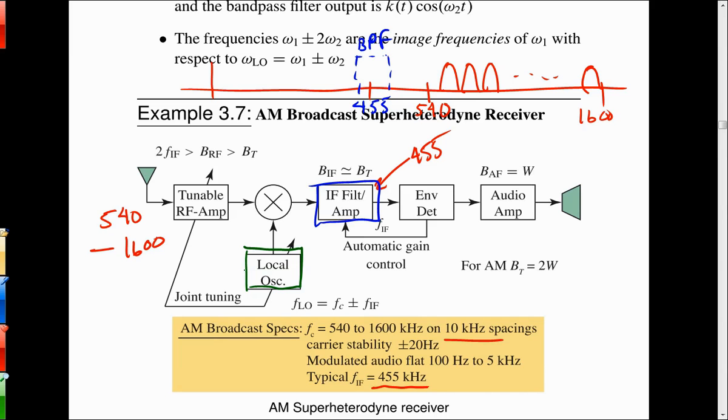But what about when you're needing to transmit it through a different kind of medium, like you could transmit to a satellite station and then from there transmit to a satellite or something like that? Yeah, and that'd probably be a good application. What Rob is saying, that you would start at a lower frequency and then you want to move it up to get it out to the transmitter and the antenna. You have a microwave amplifier, power amplifier, or HPA as they call it, high power amplifier, and it's starting at a lower intermediate frequency, which I guess would be typical of a box at RT Logic or Emergent or somebody like that.